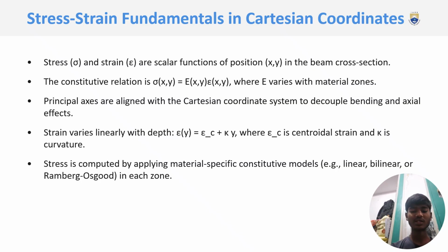Strain varies linearly with depth. Epsilon of y equal to epsilon c plus k y, where epsilon c is the centroidal strain and k is the curvature.